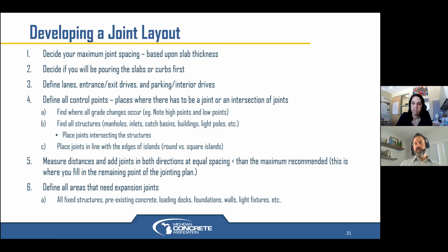So I would instead use a closed cell foam, and it comes in varying heights, or I guess depths of joint, thickness of slab, really. I would tack that around a structure prior to pouring the concrete back to isolate that structure from whatever concrete repair or slab that you're pouring up against it.